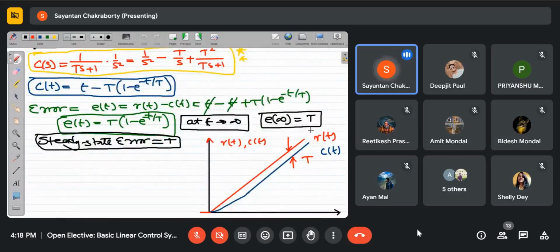So the steady state behavior of a system is input dependent, so you cannot comment anything on the steady state performance of a system just by studying the step input response. But as we already said, we can comment on the transient response part for impulse or ramp just by studying the step input.